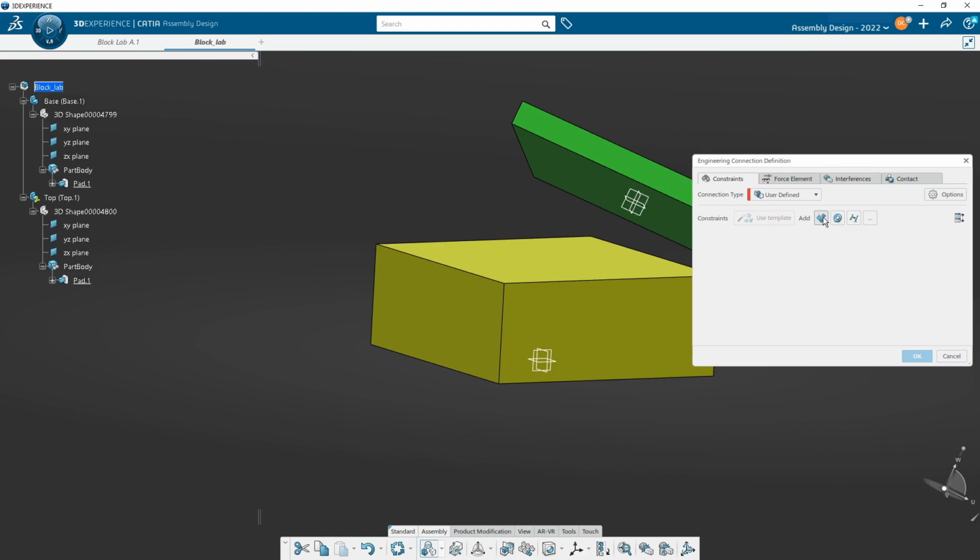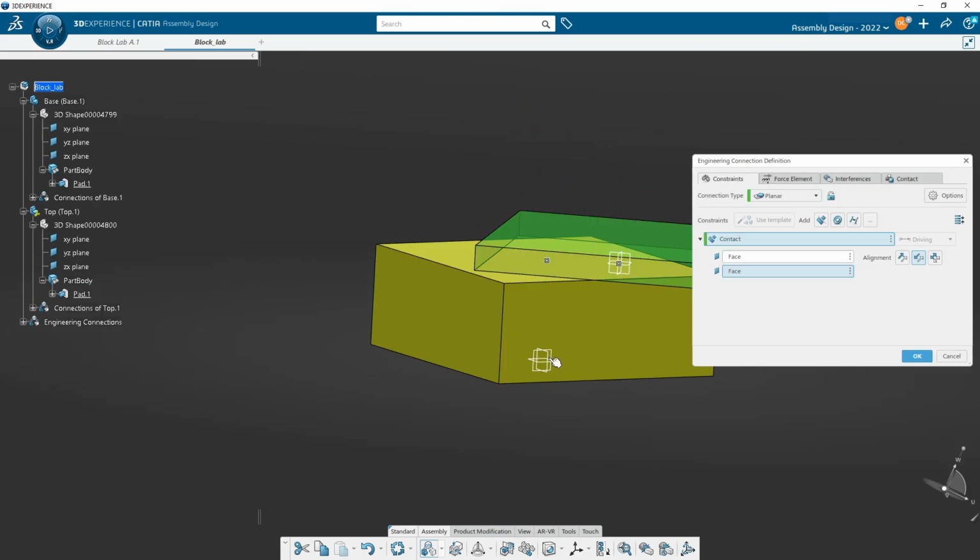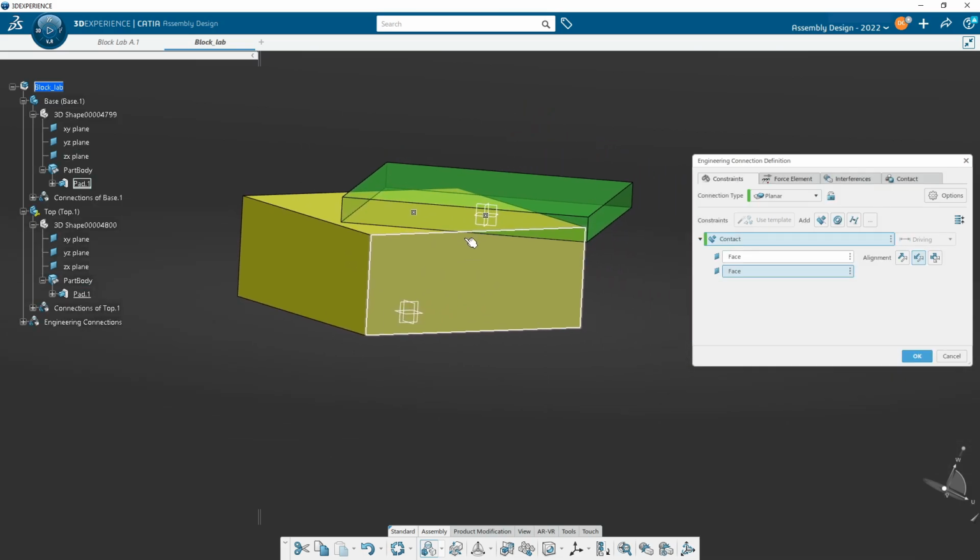what it's asking me to do in this window is saying, pick some things. Pick one of these and tell me which things you want to do that to. Okay, so in this case here, I'm going to say, okay, contact constraint. And then this window pops up, and it's going to be filled in by the two things that you want to contact. So I want this one and that one to touch, just like that.